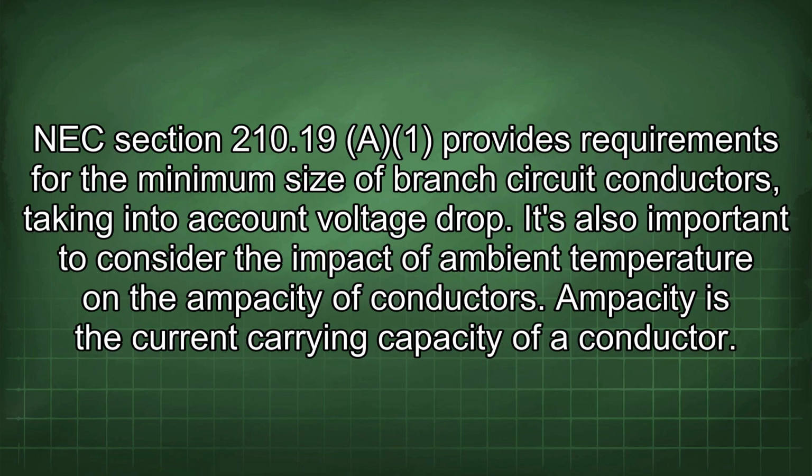NEC Section 210.19(A) provides requirements for the minimum size of branch circuit conductors, taking into account voltage drop. It's also important to consider the impact of ambient temperature on the ampacity of conductors.